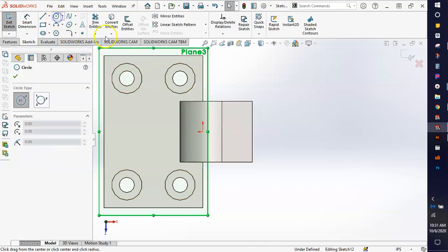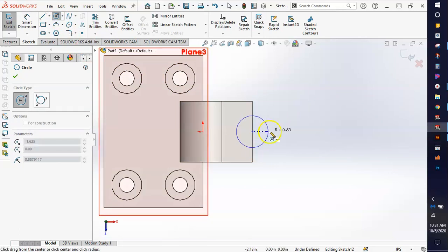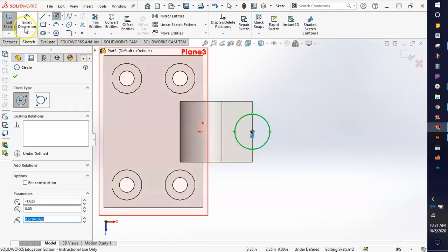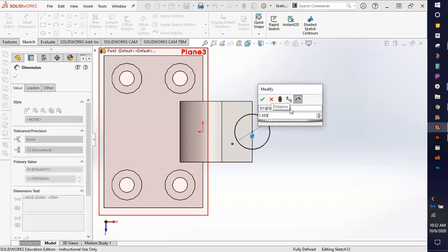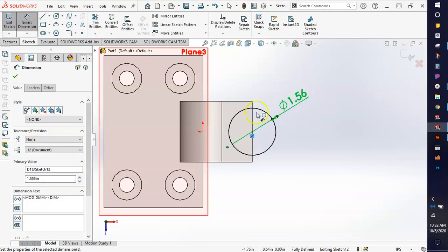Okay, so I'm going to use my circle tool, move my mouse over this line, and click on that yellow dot, and I'm going to make the top part first. That top part has a diameter of 1.555. So whatever this object is used for, it must be very specific up there if you have a weird decimal place like that. So 1.555.